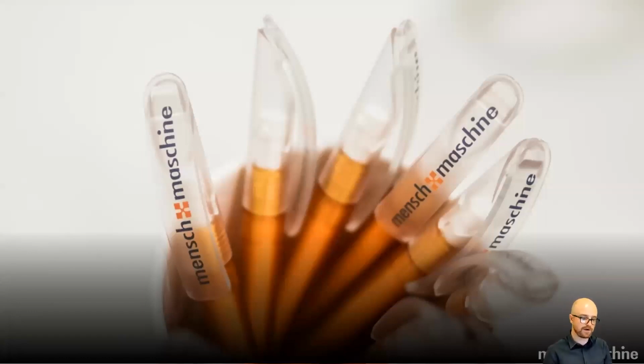So those selection sets are essentially coming from Revit, if you like, the views that you get from Revit. And at the moment, there's no way to break those down other than, like I say, within the specific clashes, basing them on object, system, or type. System's quite a good one if you're mechanical, because you can clash an entire system together if you want to, bit by bit or system by system. So that is quite useful to break those clashes down.